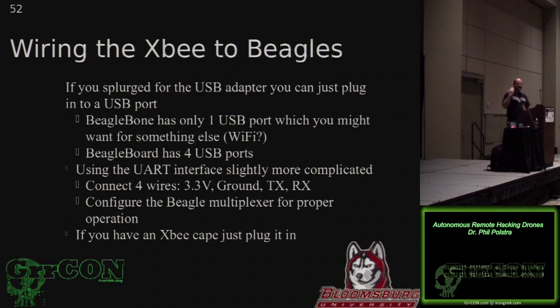Or if you have an XBee cape, like Logic Systems, they sell an XBee cape. Theirs does not have the EEPROM on it that identifies it. So you have to manually say, this is what I am, and please load stuff, Ubuntu or whatever, which can be a little bit of a pain. If you have an XBee cape with a properly formatted EEPROM on it, in theory, you just plug it in and it goes, oh, I see that you're an XBee cape, and it loads itself. Okay.